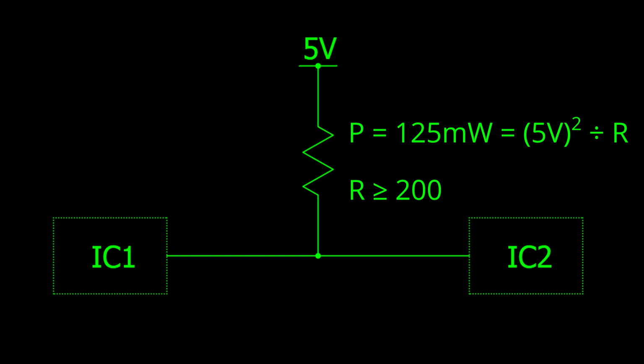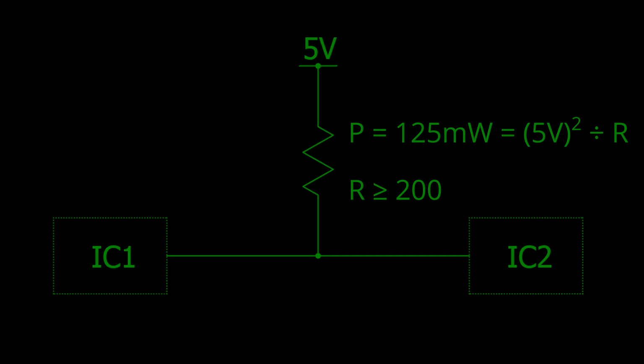The power consumption of components is something that is often overlooked in designs and is also a common point of failure for prototypes. Make sure you are using appropriate power ratings and you won't have any issues. Well, at least from your resistors.